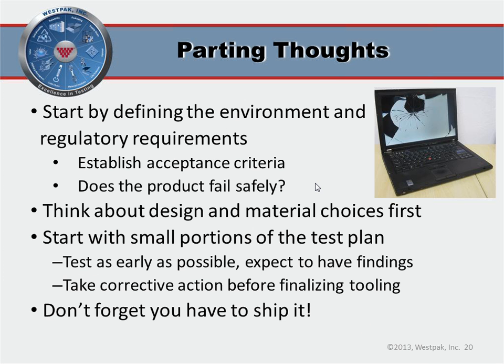All right, some parting thoughts on testing here for you. We have a pause for questions just after this. Again, start by defining the requirements. What environments will your product be exposed to? Are there any applicable regulatory requirements? And establish your acceptance criteria. What's the minimum your product has to do? What are the nice-to-haves? One thing to keep thinking about is, does the product fail safely if it's exposed to some extreme environment, like it gets too hot? Do the overtemps work and does it shut down? You should check all that.